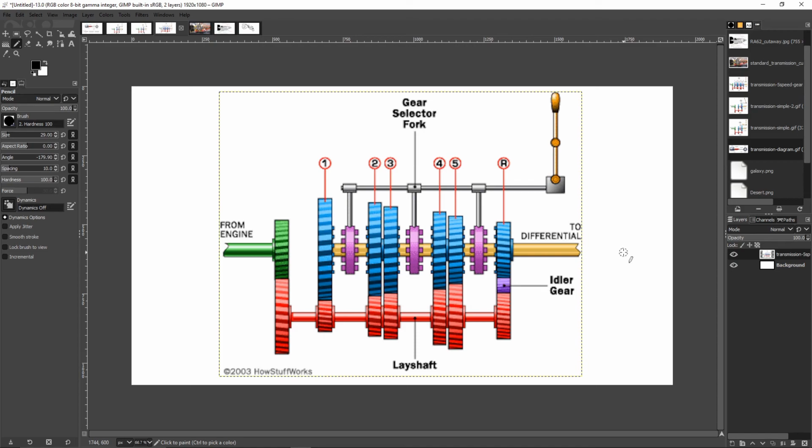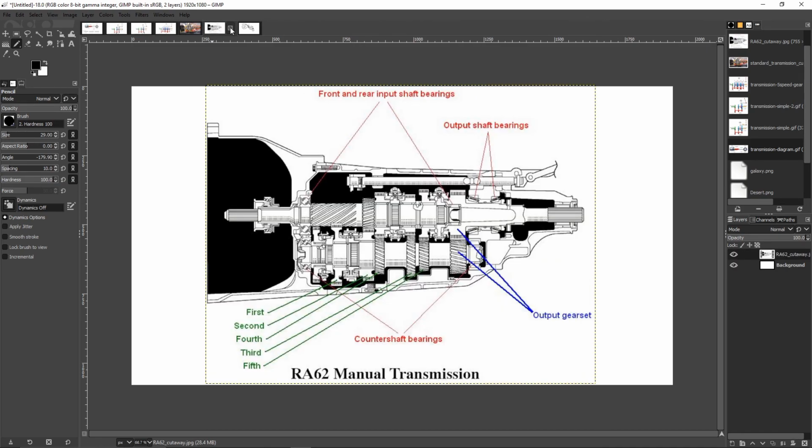So if you know somebody that likes to put it in reverse, start backing up, push the clutch in, and then jam it into first before they stop the vehicle, that is going to destroy this idler gear, the synchronizers, and this gear set here that is reverse. I've seen many customers do it. Don't be that person. You will absolutely ruin your transmission.